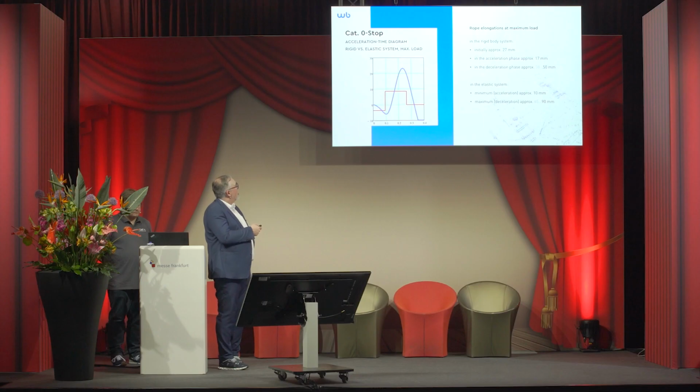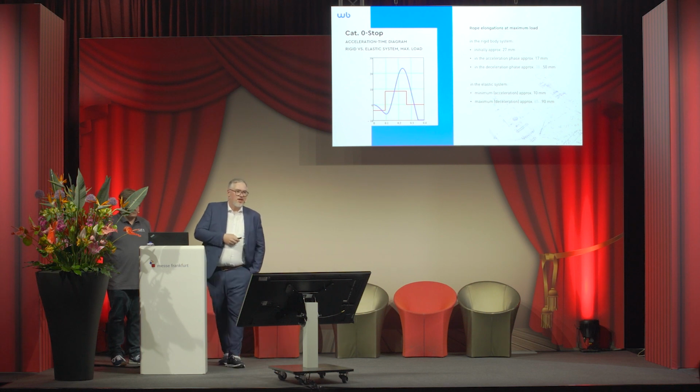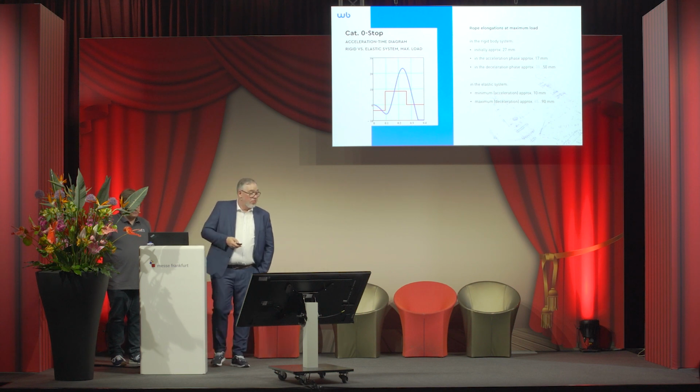So you can either simulate it, and you see in the elastic system, once the event is happening, in the acceleration phase, this takes a little bit longer to release the rope, and when the brakes apply, when the braking torque applies, the whole acceleration of the load overshoots the values in the rigid system, even by a factor 2.